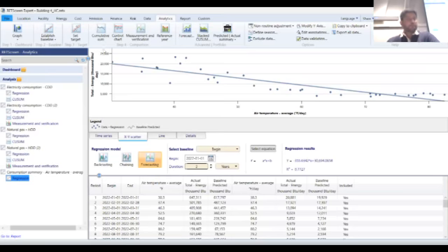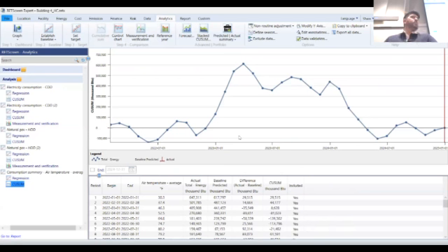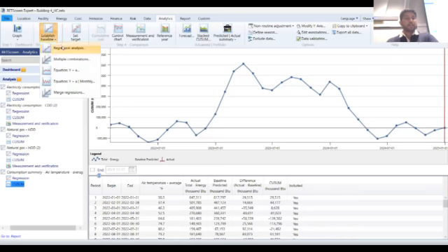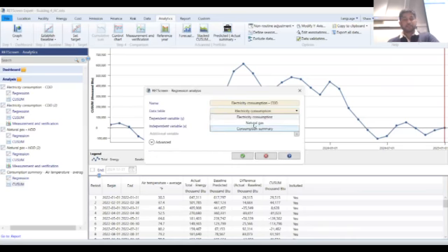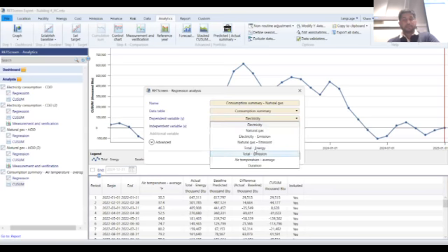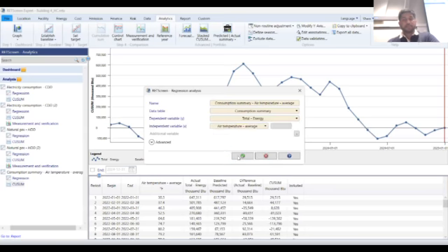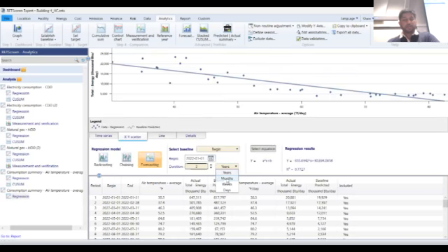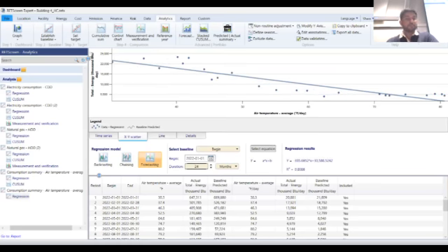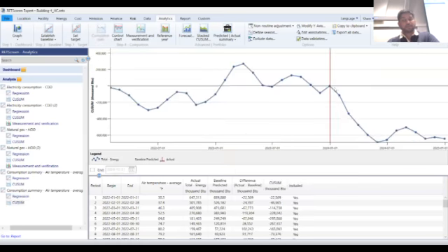There you go. I have a graph. Again, I do a cumulative sum. And at this point, I already know that all the measures were completed by end of 2023, so I don't need to go by March or December. I don't need to separate my savings. I can just directly establish a new baseline. Total energy, compare it with air temperature average. I change my baseline to 24 months, which is 2022 and 2023, do my cumulative sum. And clearly the energy starts going down.